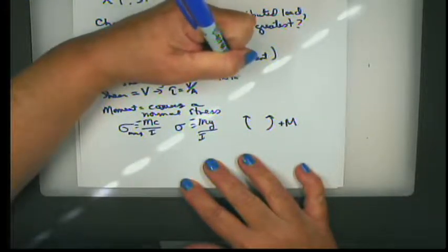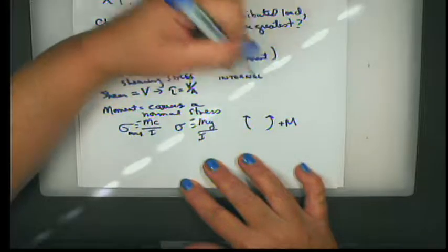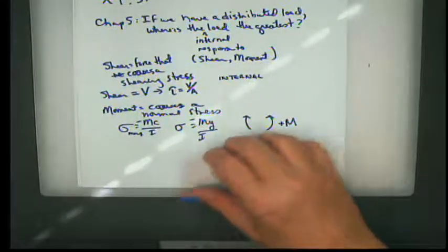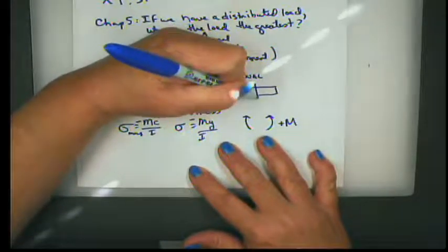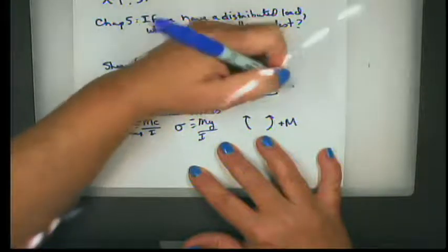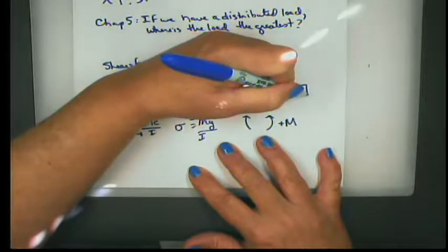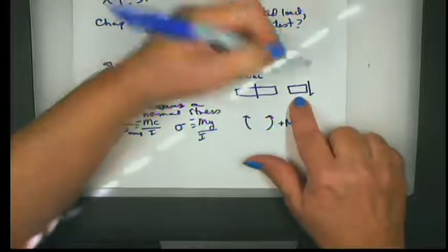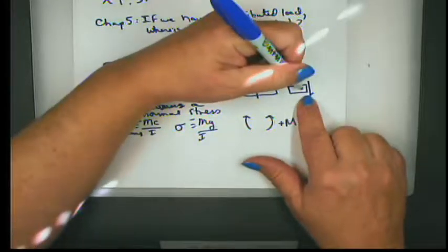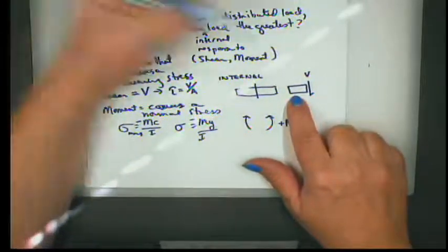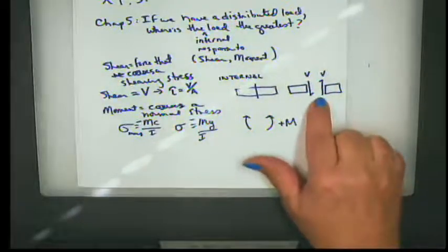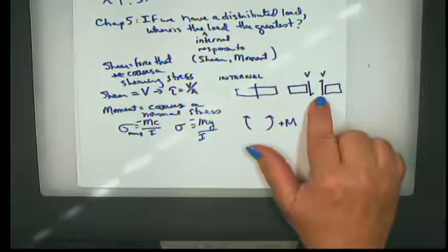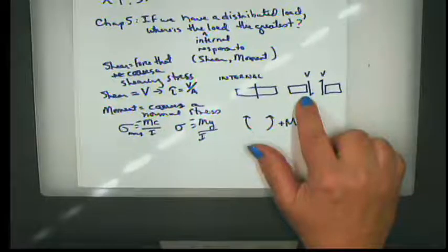It's a little bit trickier, because if you think about it, if you have a beam and you cut it in the middle and there's some shear, if the shear looks like this on the left, in other words, if I've cut it on the right side and the structural member is to the left, it's going to look like this on the right. Because they still have to be equal and opposite, and if they're not equal and opposite, then something's going to move or break.